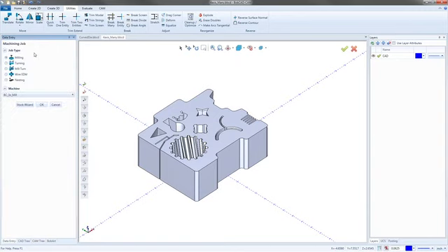Now, when we're doing Wire EDM, we have to first of all choose Wire EDM, but then down here you have to pick your machine. So we have a bunch of Mitsubishis, a bunch of Fanuc, some Charmilles, some Agie. There's a list through here. Now, I will start by saying not every one of these posts is perfect for your machine. So make sure, if your machine's built into the system, to test the post right when you get it. But if it doesn't work, just work with the tech support guys, work with the post guys.